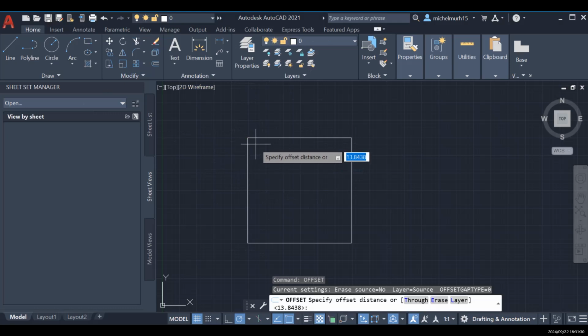I'm going to go slowly. I'm going to start with this one here. I need to create another parallel line to this initial horizontal line here. So of course, I'm going to press offset, the first step. In the second step, I'm going to pick this endpoint, and I need my offset to be 0.5. I'm going to just type 0.5. The offset means the thickness of the line, so it should be 0.5. I'm going to press OK.